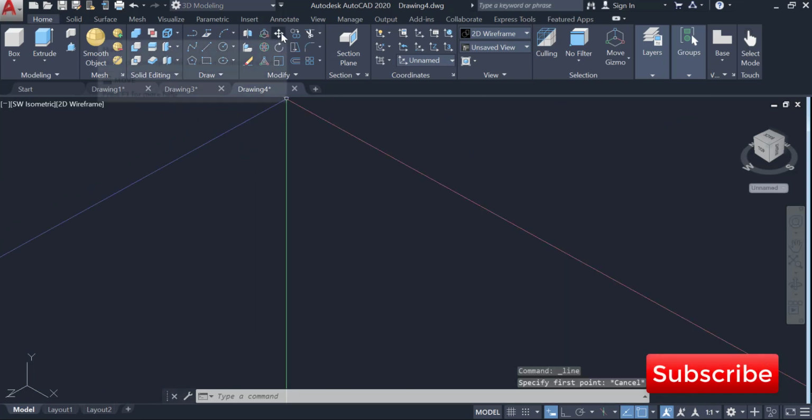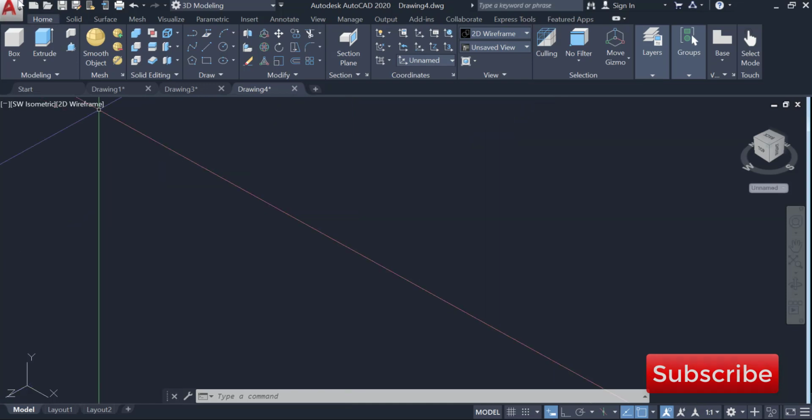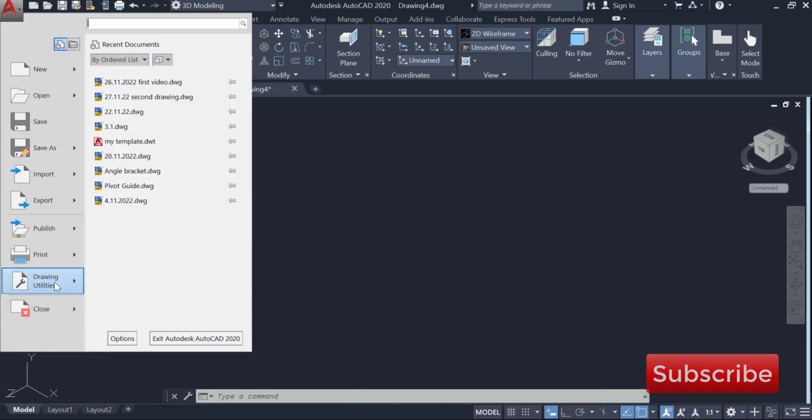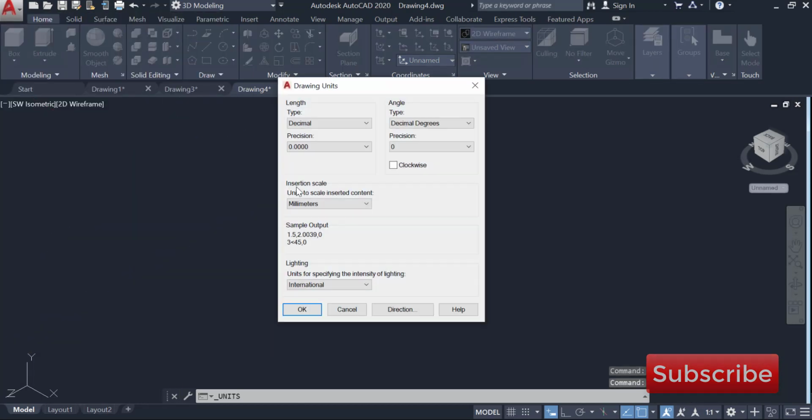One thing, maybe this is the bonus. If you want to set the units to millimeters, what are you going to do? Click this AutoCAD, then drawing utilities, units. I won't change here, so it will be decimals. We need decimal precision. Maybe you can use this one in millimeters.